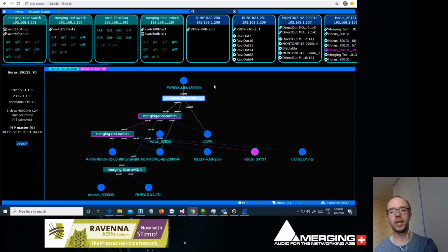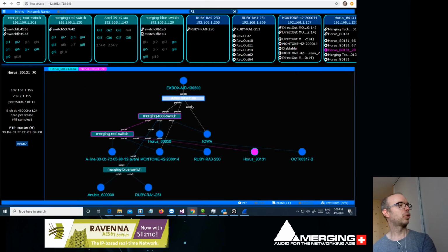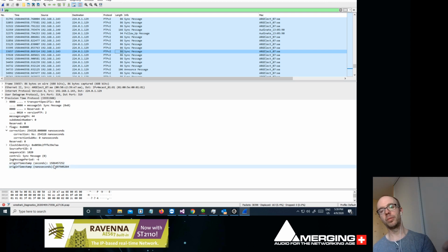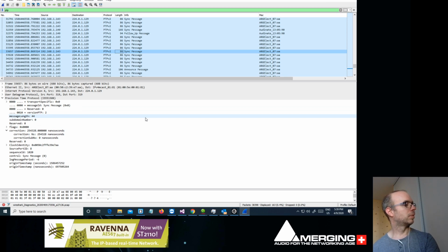Okay, so yes, two different modes of PTP on the switches: the boundary clock and the transparent clock. And we can see also that in the sync message we do have a correction there, but that's their own recipe of the switch. Maybe it's not correcting the origin timestamp, it's taking them from the master, and then everything is happening as a correction. But that behavior is different on each boundary clock.